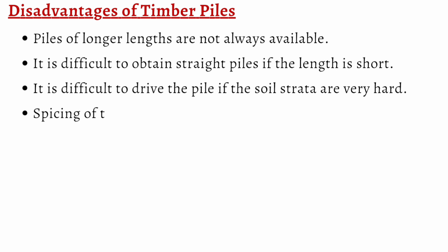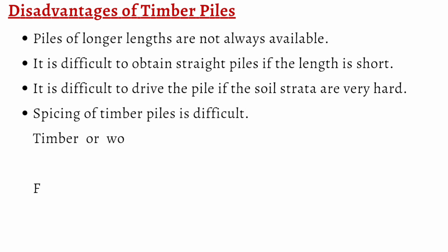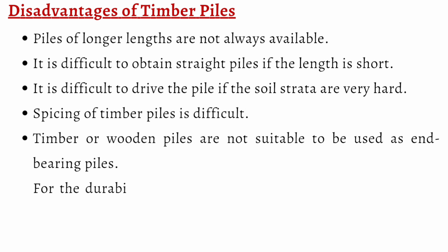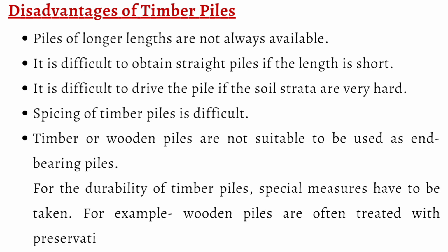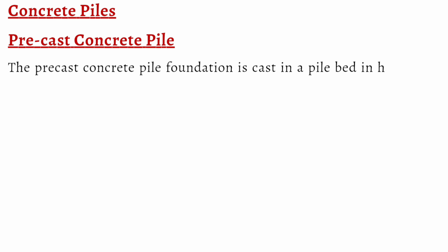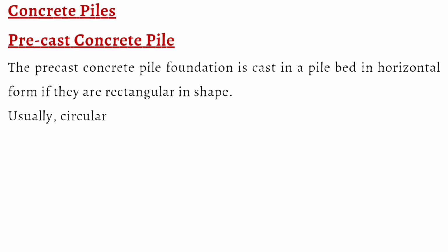The length of the pile is usually 20 times the top width. They are usually designed for 15 to 20 tons. Additional strength can be obtained by bolting fish plates to the side of the piles. Advantages of timber piles. Timber piles of regular size are available, economical, easy to install, with low possibility of damage. Timber pile footings can be cut off at any desired length after installation. If necessary, timber piles can be easily pulled out.